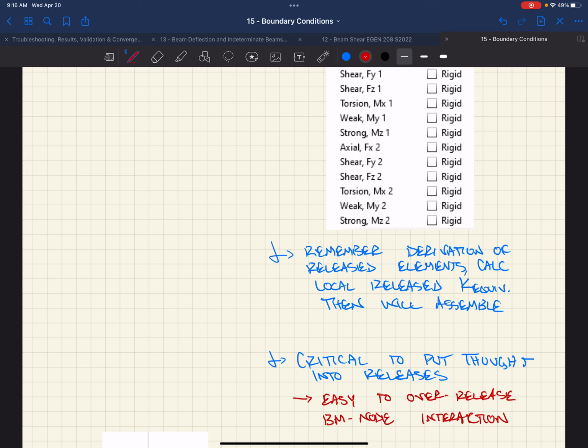You can capture that within the model. The engineering building has a proprietary system called side plate. In order to make sure there's strong column, weak beam, they mash a bunch of huge steel plates on both sides of the columns and the beams. So you're basically cheeking it, putting two plates on both sides. What that does is it makes the connection really, really stiff. That means the beam framing into the beam to column intersection, and the column framing in, are really, really strong and robust. They're stronger than anywhere else in the frame.